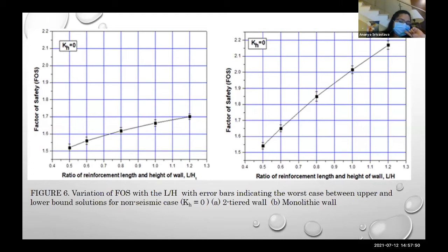This may seem a little bit flashy, so why not construct my monolithic wall? The reason behind it is that you need to give a very deep excavation. Now for walls which are as high as 40 meters, you cannot provide such backfill values and backfill soil transportation costs. Under such situations, construction of a tiered wall would still be beneficial.